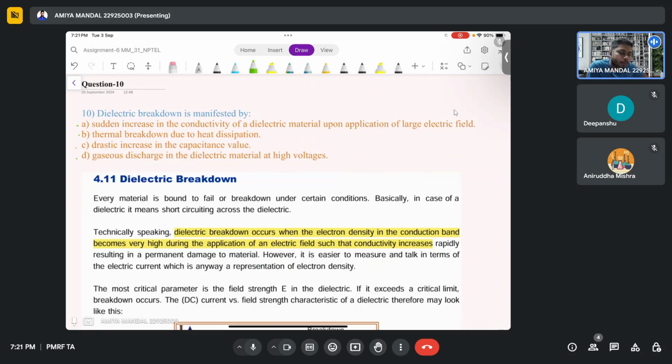If the insulating property is lost, the material becomes conductive, meaning electrical conductivity is generated after the breakdown. There is a limit of induced or leakage current inside the material. After that limit, with the application of electric field, temperature, or any external force, the dielectric behaves as a conductive material. This limit is called the dielectric breakdown limit.